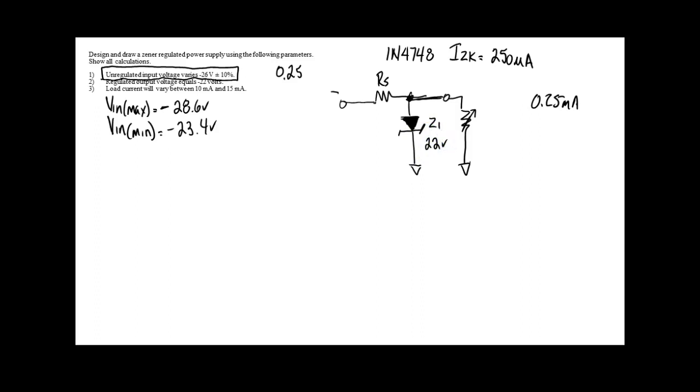Well, it's a 22 volt Zener. There's no such thing as a negative 22 volt. So all I'm doing down there is putting the VZ. There's no such thing as a negative Zener. Yeah, you always put it reverse bias.